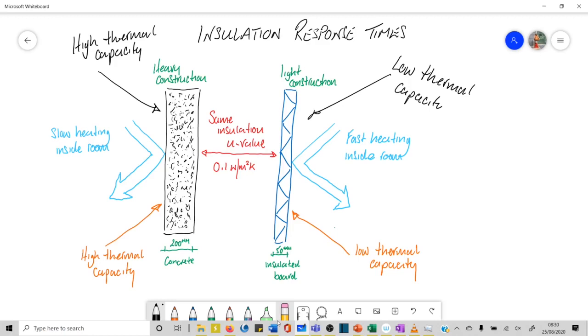Now, if we move on to cost, there's an advantage and disadvantage there, obviously. On the concrete side, we've got 4 times the thickness. So we've got the cost of concrete. Prices do vary, but it is approximately £110 plus the dreaded VAT per cubic meter.